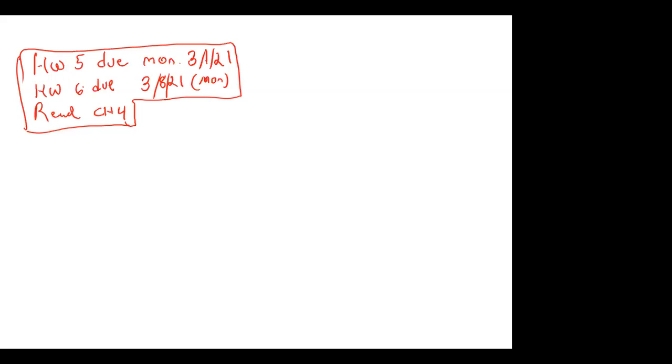16. Use Kmaps to simplify the following function in sum of products form, taking advantage of the don't cares provided. Well, it turns out you always have to take advantage if they help you, and they will help you if they make your loops bigger.